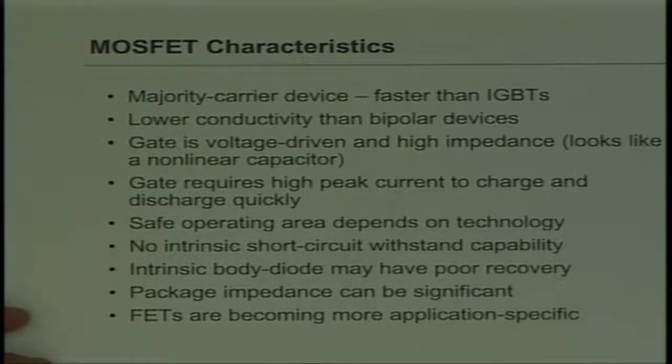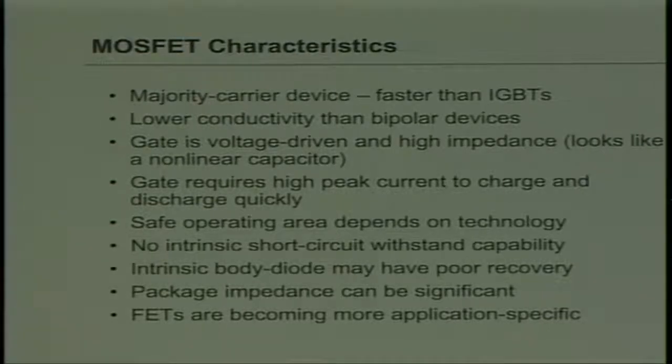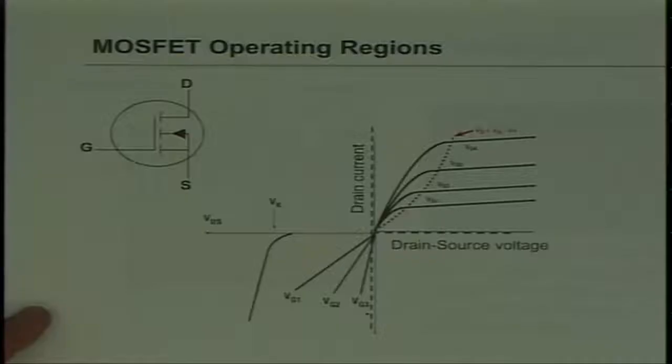The package impedance can be quite significant. We're talking about FETs now that are a milliohm or less, and the package itself becomes a huge part of that overall impedance. And as I mentioned, they're becoming pretty application specific.